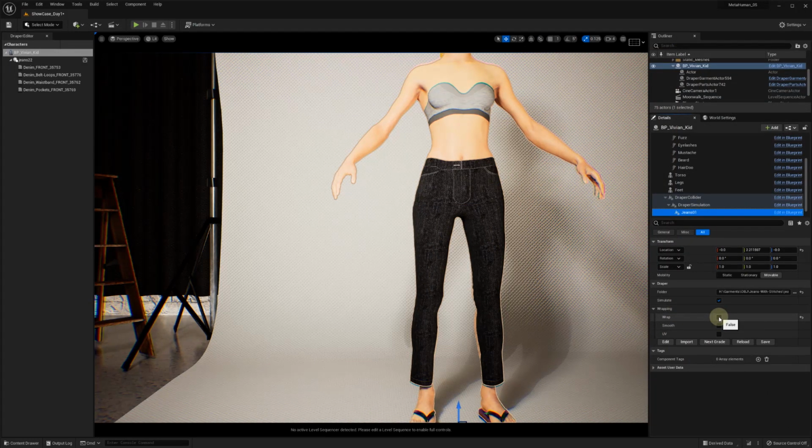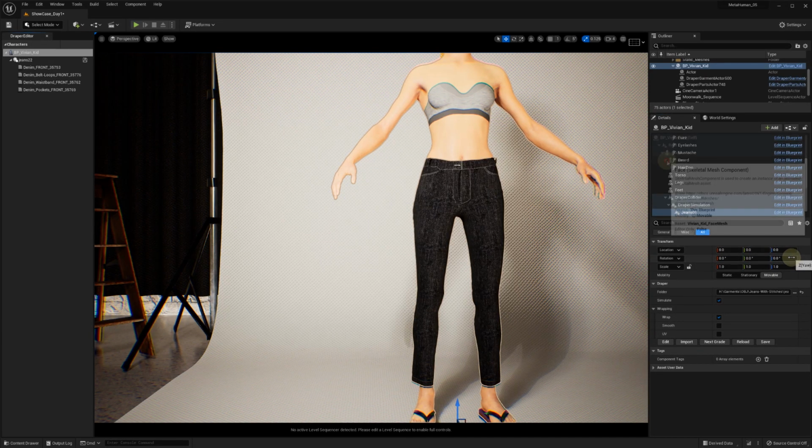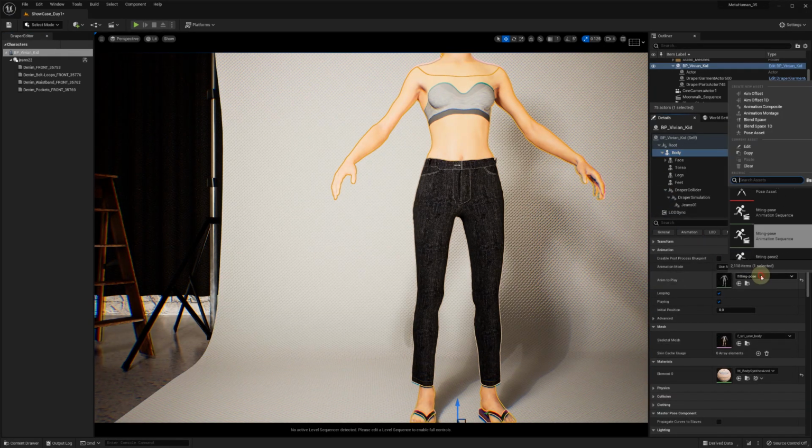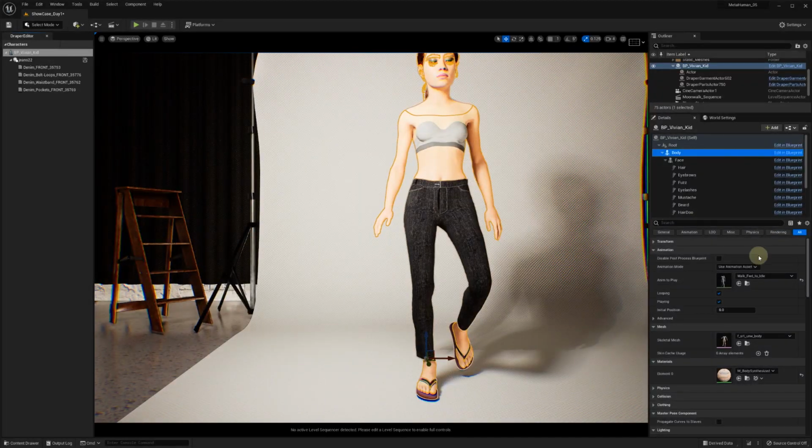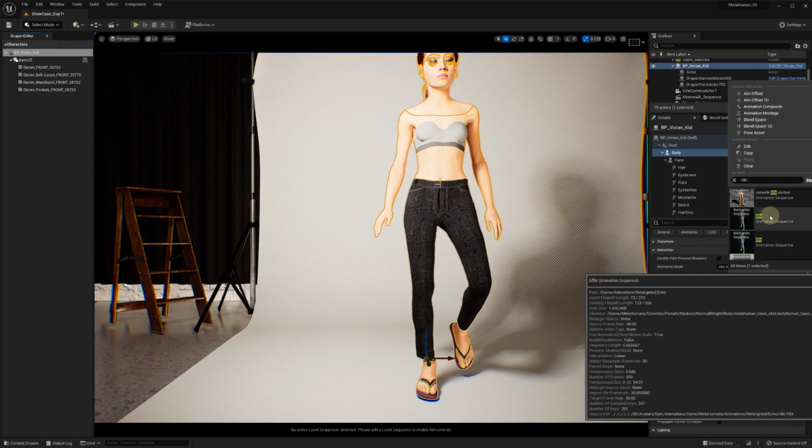We can now turn the wrap option on and remove the transforms that we used for the garment positioning. The wrap will now remember how the garment was draped around the avatar's collider mesh. Wrapping can be handy when you want to change the avatar pose. The garment shape will change with the avatar's pose when the cloth simulation is not running.